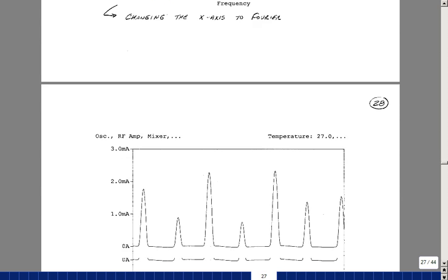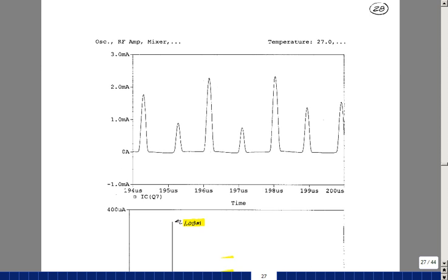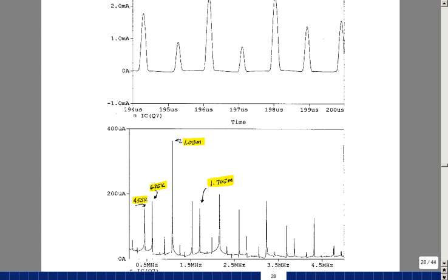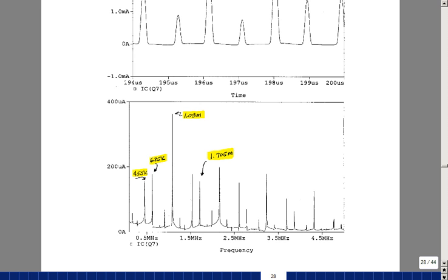Also look at the current in the collector of transistor Q7 now that I've got a carrier voltage of 0.1 volt. You can see now the currents are going up and down, so we've got more frequency components here. But again, the period of this is the reciprocal, which is 1.08 megahertz. So I did also the spectrum analyzer, and you can see these four frequencies again. The received signal around 624, the oscillator of 1.08 megahertz, the product of those two creating these two frequencies. But even with all this stuff here, the tuned circuit's only going to let this one through. And that's how the oscillator works.